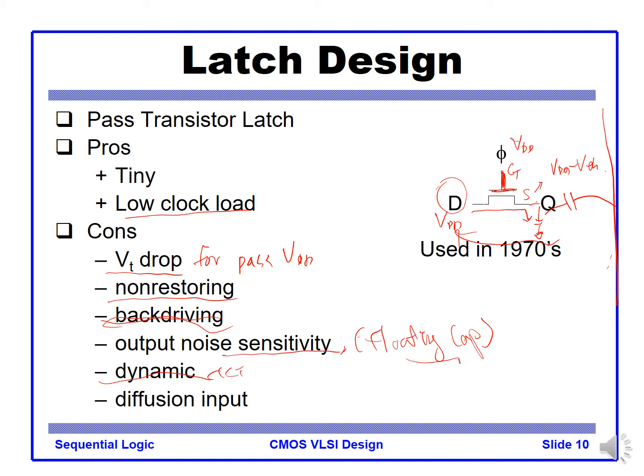All the problems that domino circuits have are also present here. And the input sees diffusion capacitance rather than gate capacitance.